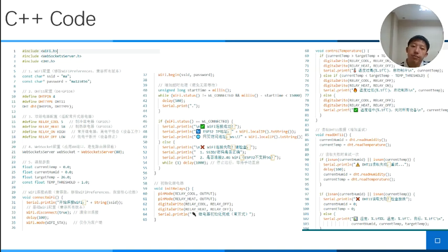Serial communication. The ESP32 interacts with the sensor and actuator through the serial ports, reads the temperature and humidity data from the DHT11, and forwards control commands to the LED at the same time. Next, let's look at key code segments.